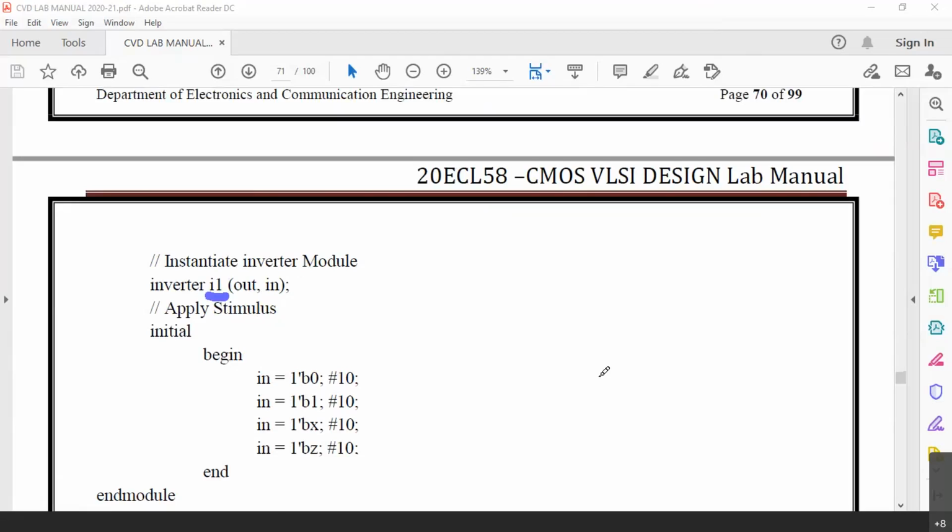You already know that all the combinational logic are concurrent. In the sense, when you write a code for a combinational logic, you don't have to use the wordings like initial or always. For that matter, when we wrote the code for inverter there, we did not use always there, because inverter is basically a concurrent execution as such.